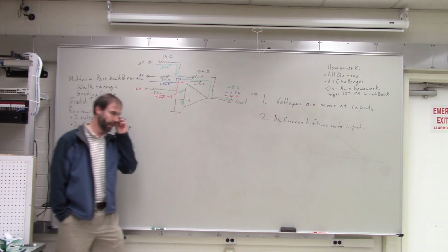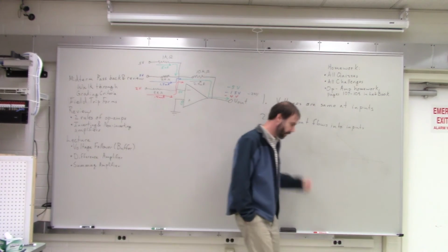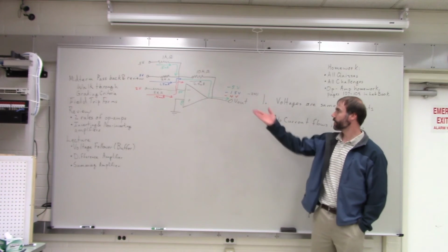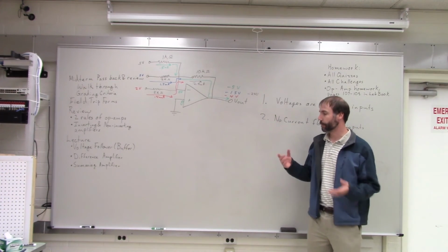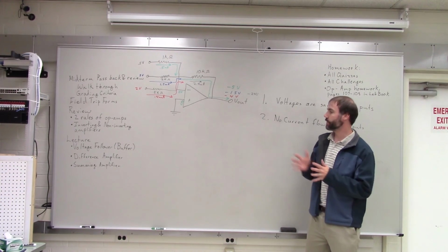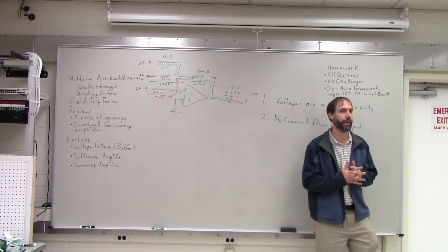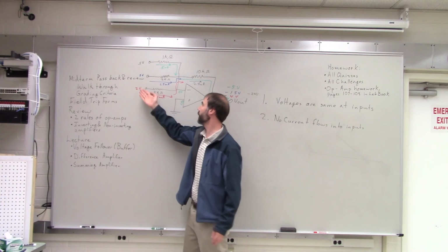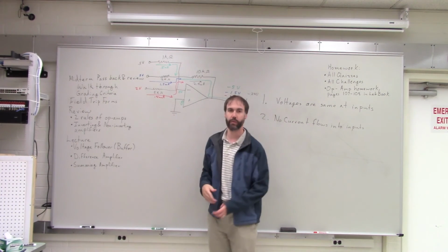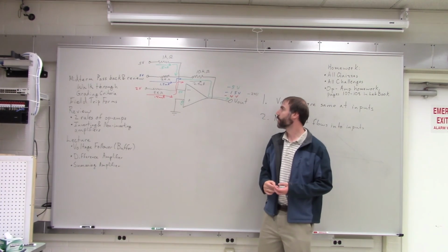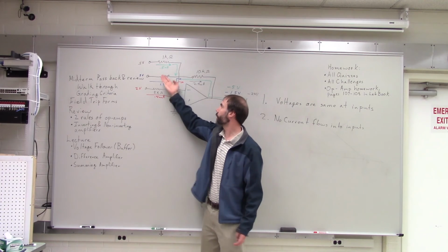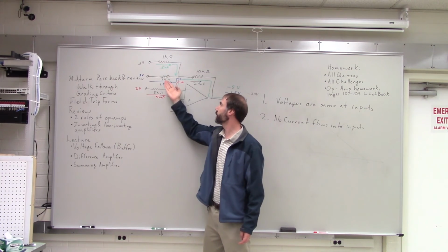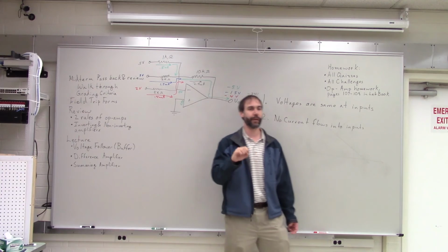Okay? So remember I was saying we could use this to mix audio tracks together, right? If we wanted to do that, we would connect one audio track to each one of these inputs. We could add more inputs also if needed. And then instead of just having a fixed resistor for each one of these, we could have a variable resistor.